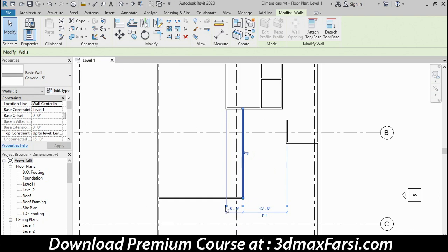Now, all I have to do is click and hold down that little dot and drag it until it highlights the preferred reference, like this grid line, and let go. That will move the temporary dimension. I can activate the number and type in the value I want. Now, this time I want both feet and inches. Now, to get feet, you've seen that just typing in a whole number and pressing enter, Revit will interpret that as feet. But what about feet and inches?